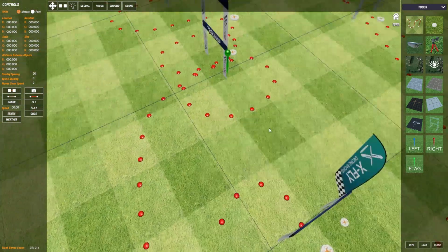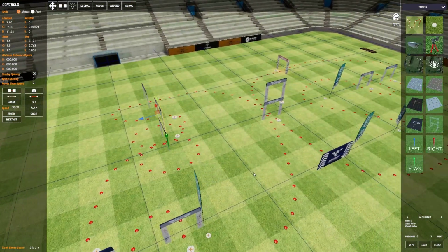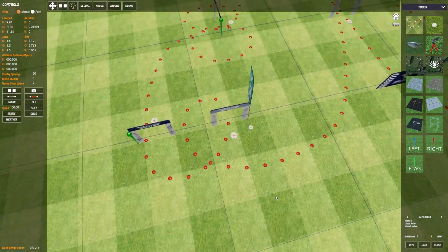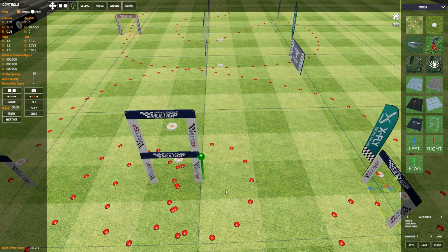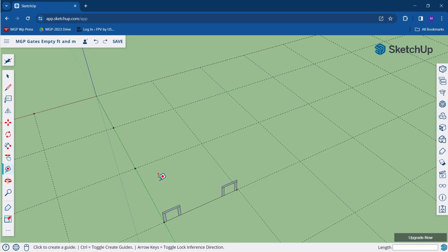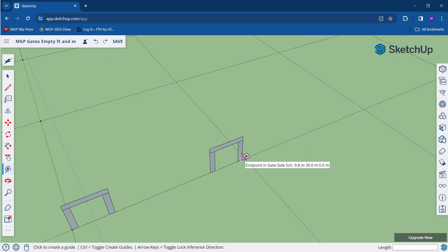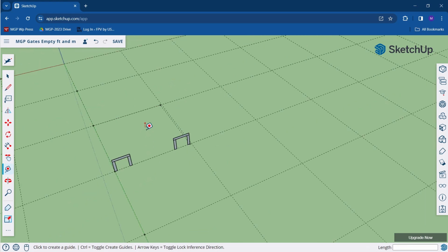Now let's see, we had a couple. All right, so now we know this gate. This is pretty easy because AK does a really good job laying out his tracks. So we know this gate is in line with this gate, but it's on this arc. So now we know that that double gate is perpendicular to this gate on the 10-meter line. So all we got to do is click this end point, go, and there's 10 meters, and put that little dot. The other way we could do it is we could measure up from here up to here. 9.8, that's what we said before.